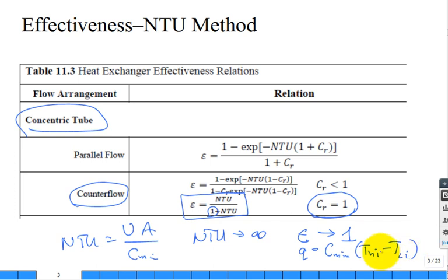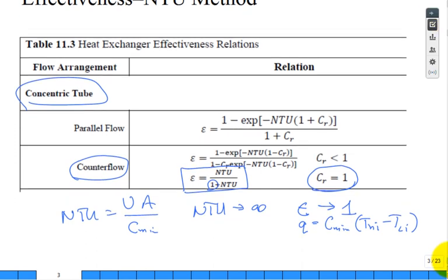But the heat capacity rate's the same whether it's hot fluid or cold fluid. That's the same as saying C sub R is 1. So I need to move this out of the way, maybe scoot down a little bit. So this is from my rate equation, how it's controlled by the area, the overall heat transfer coefficient. My energy balance equation for the hot fluid is Q is equal to heat capacity rate of the hot, temperature hot in minus temperature hot out.